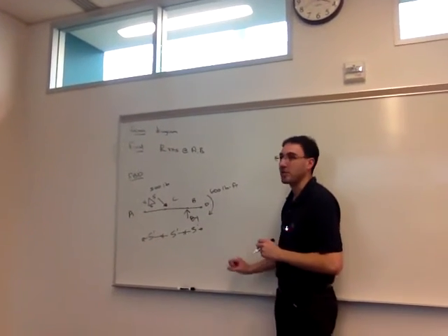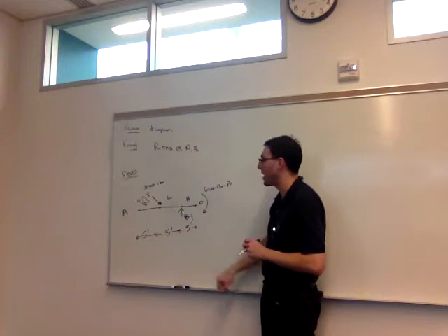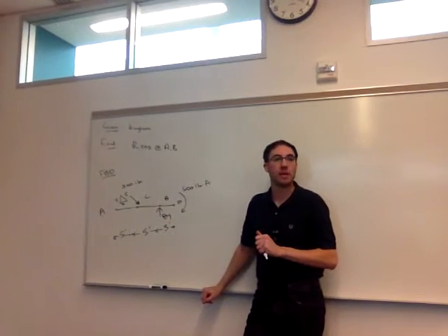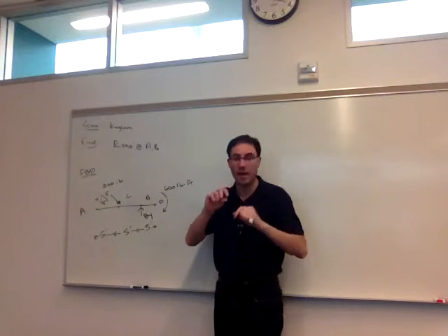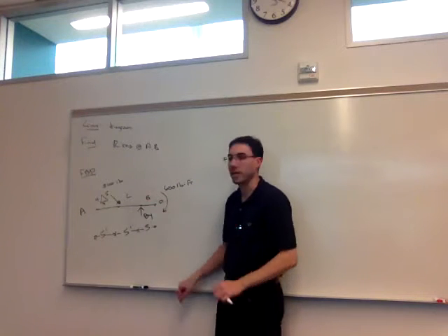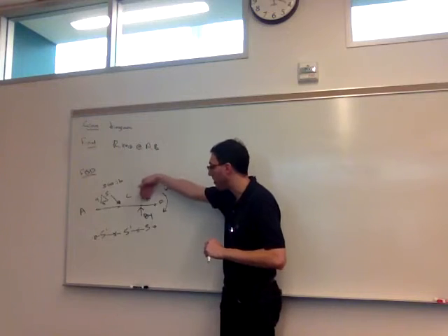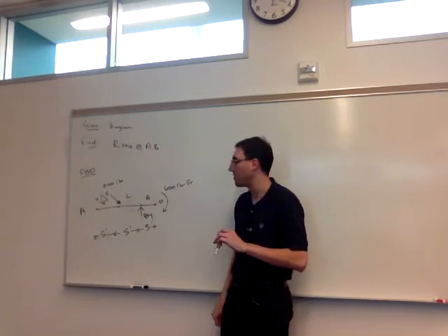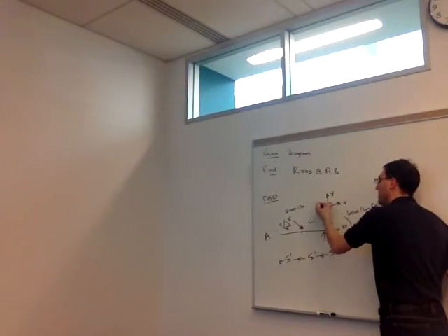And then if we think about rotation about point B, can the beam rotate about the z-axis at point B? Right, so the ball does allow that, even if it's just a little bit, it does allow it to rotate if it wanted to. So we don't put a couple at B. So the only reaction we have is By because it can't move down into the ground. While I'm at it, I will have a coordinate system.